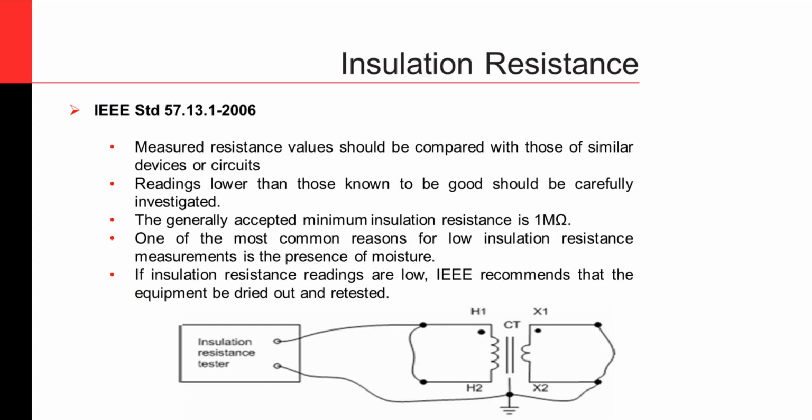There are very interesting scenarios where the CT was still working when the insulation had completely melted, and there are instances as well. So depending upon my insulation resistance test, I will have a better idea of whether the CT is disintegrating or not.